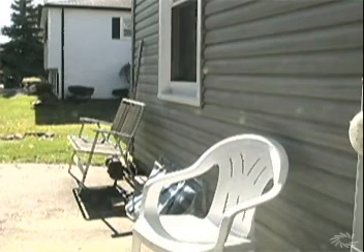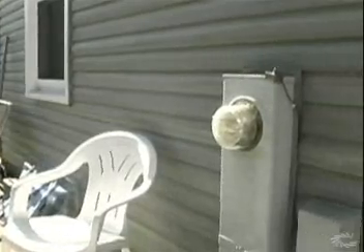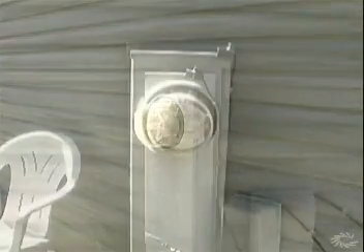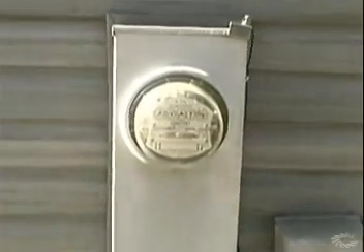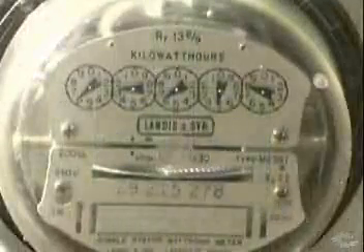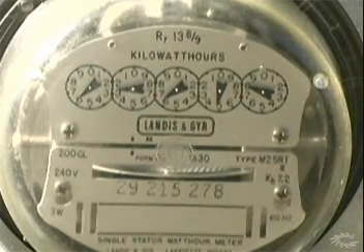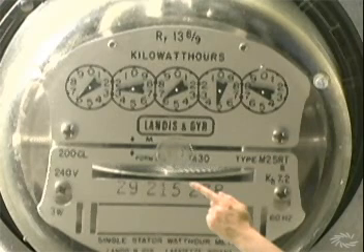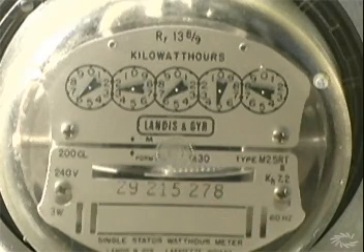The power company keeps track of how much electrical energy a home or business is using by reading electric meters, which are often found outside a building. The main electrical wire from the power company goes to the electric meter, and then into the circuit box of the building. The electric meter has 5 dials, each with 10 numbers from 0 to 9 written on them. An arrow on each dial moves around as more and more electric current flows through the meter. See the disc spinning? That disc is recording the flow of current into this home. It will spin very fast if a lot of electrical devices are being used at the same time.